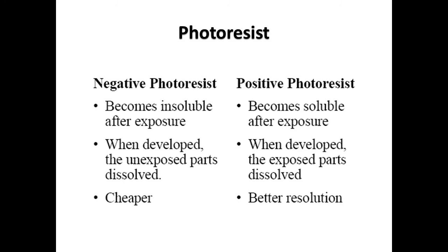The characteristic of negative photoresist is that it becomes insoluble after exposure. When developed, the unexposed parts will be dissolved. It's cheaper, but the disadvantage is that it will have lesser resolution than the positive photoresist.